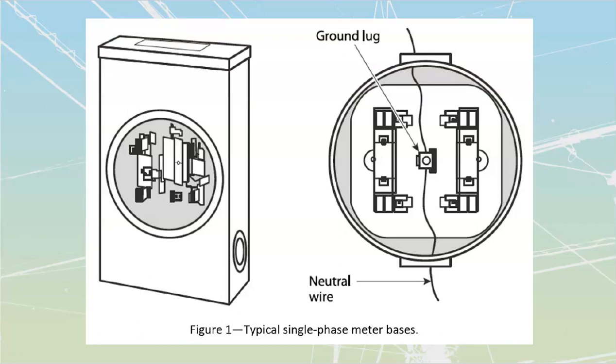it is allowable. What 6-102 prohibits is that we are not allowed to have, like, two 120-240s onto a building, because then people start grabbing stuff off the wrong neutrals, and there's cross wiring, and it all turns into shambles. There are a few exceptions to it. When we have some emergency equipment, there's this thing called a fire pump that is going to just run the sprinklers in the case of a fire. But outside of that, coming to a building, you can only have a single service per voltage level coming in.